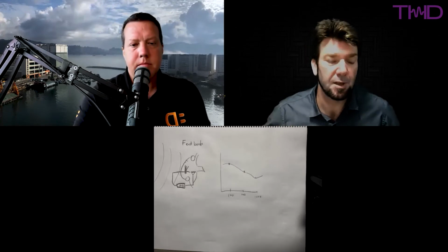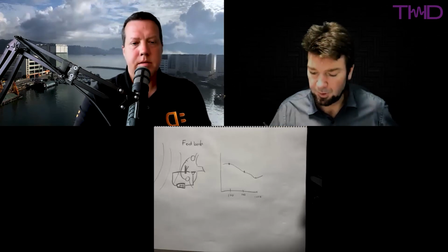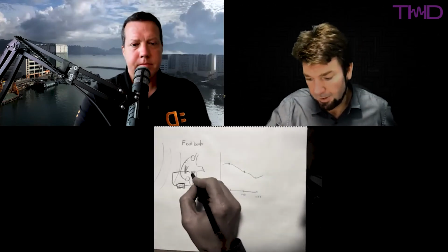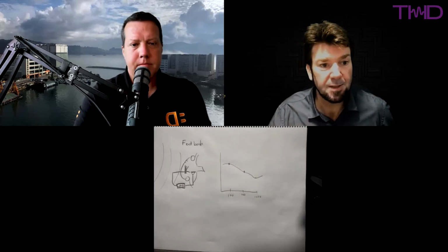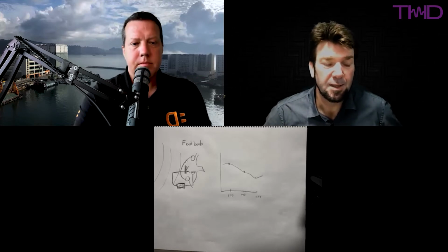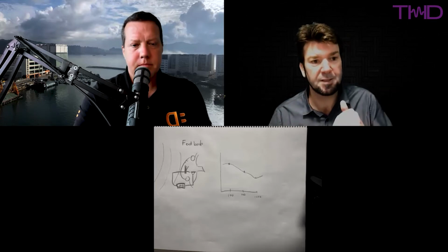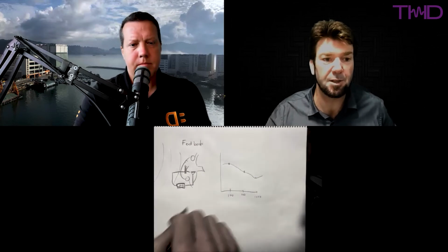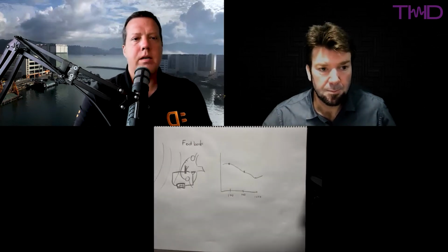Then you have this whistling problem. We generate a feedback loop. So you have to try and construct your filter so that in this feedback loop, at the frequencies at which the phase has gone past halfway, getting close to being in phase, adding the sound waves again, you have to have such a low gain, a negative gain in fact, so the sound is diminished on each loop, and then you don't have that squealing problem. Okay.